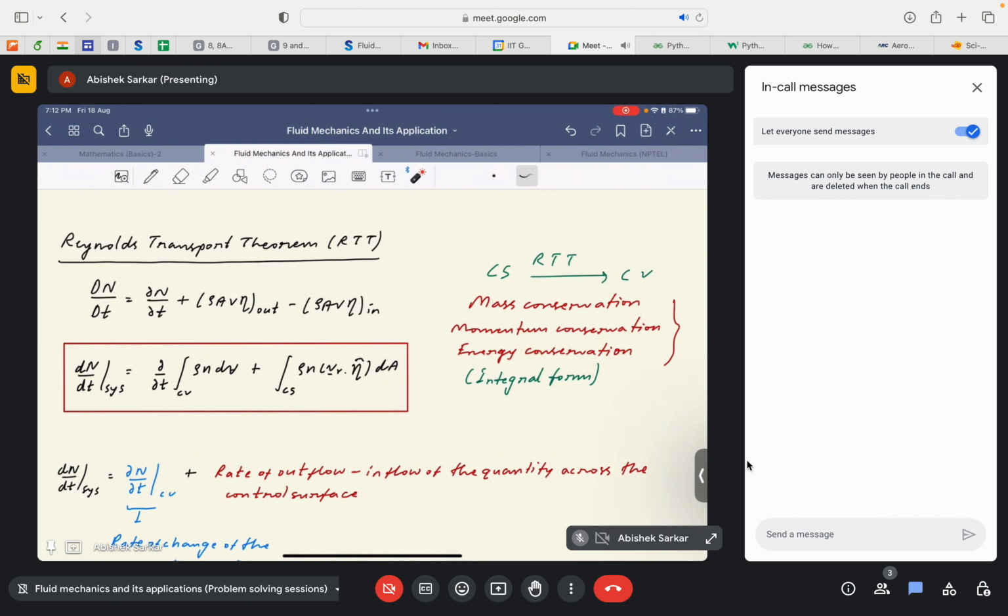If we solve fluid mechanics problems by following the Lagrangian approach, following each and every fluid particle in the flow domain, it will give very accurate results, but it will be very tedious and difficult to handle all those governing equations for each fluid particle. To skip past such tedious nature, we saw how the control volume approach helps eliminate such calculations, and how it came out to be very useful for most of the fluid flow problems that we are going to deal with in this course.